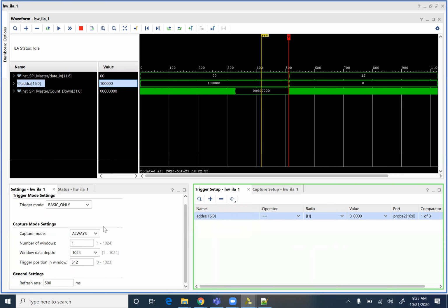It's going to be a hard one. We're not adding anything new. I will reiterate that again, other than the in-out pin and writing to memory instead of just reading from it. Those are the two new concepts. The big thing about this is it's now a big state machine, right? Lots of states. I strongly encourage you, no matter how you design the SPI interface, to use the two-state method for both read and write.